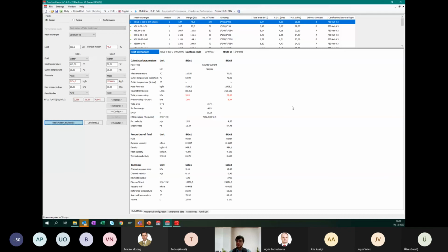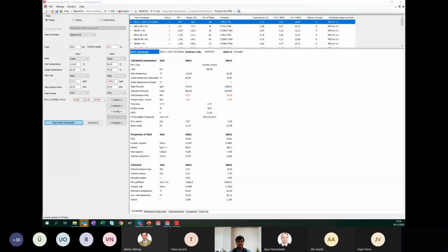Together with more efficient pumps, which we have, the modern generation of pumps consume less electricity for the same pumping capacity. That's why, in general, what we see right now for new buildings and new district heating networks, which work on renewable sources of energy, is that the available pressure drops for calculations are being increased up to 30, sometimes 35 kilopascal on both sides.